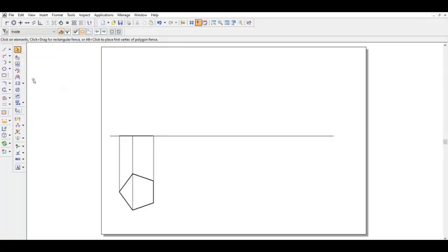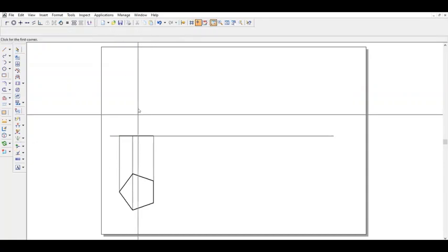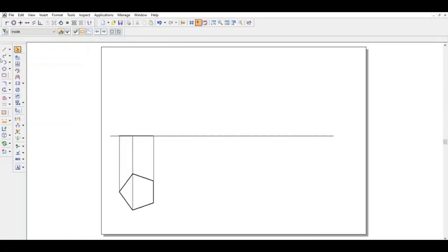Now he has given some inclination here with respect to this. When inclination is given, it is easier. Just select this, go for make a copy, move copy. Since it is resting on a corner, select this corner and make a copy of this. Place it there. Go for rotate. When you are rotating, this particular point is stationary, it is at rest. The only thing which is moving here is this particular point. Now here you can go for either the rotation angle or the position angle. Just give it 30. So the angle between XY and this particular line is 30 here.